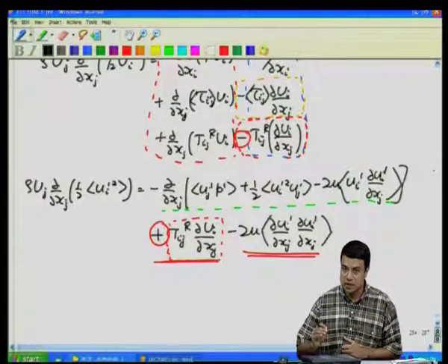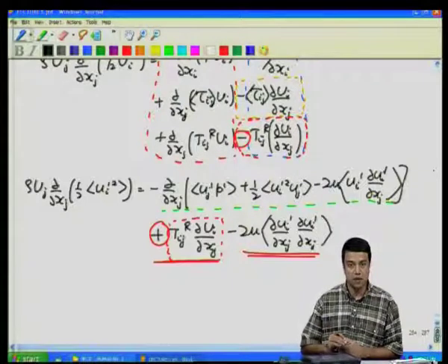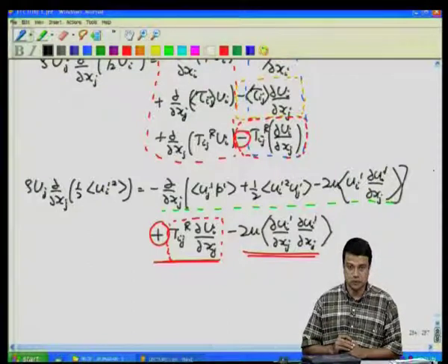Because the viscous dissipation of the fluctuations is much larger than the viscous dissipation due to the mean flow, you get a friction coefficient or a drag coefficient which is much larger than what you would expect for a laminar flow in a turbulent velocity profile.